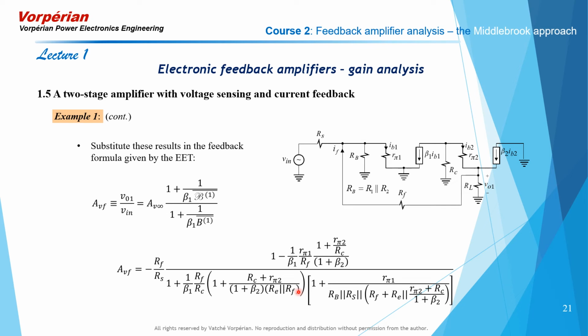Now let us see if we can see all this on the circuit diagram itself. Okay, so if we let β1 go to 0 in this picture here, then there is no longer a path of the signal through the amplifier to the output. The only path that we have from the input signal to the output is through the feedback connection.